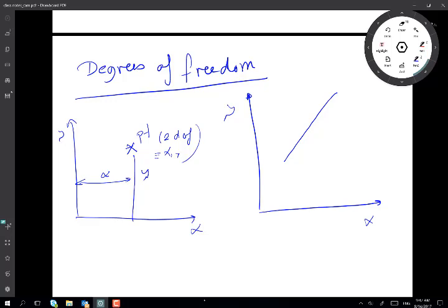How about a line now? If the point develops into a line, we need 3 pieces of information to draw the line. We need x, y of a point, and also we need the angle of the line. A line is really a member of a planar linkage, because the line connects the joints. In linkage analysis, we don't worry much about the actual shape of the link.